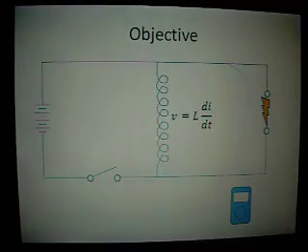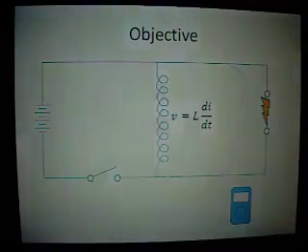Now, as I've drawn it here, my diagram shows the spark occurring over to the right across a couple of electrodes. In reality, this circuit probably wouldn't function that way. In reality, the sparking would occur across the switch as the switch is being opened. So this is a little bit of a problem that we have to overcome.